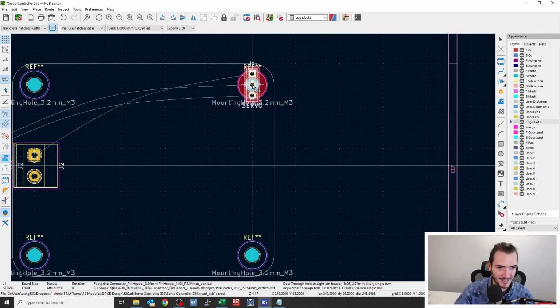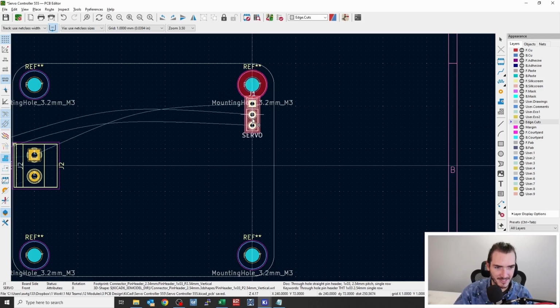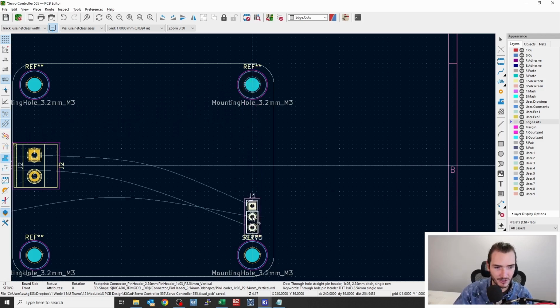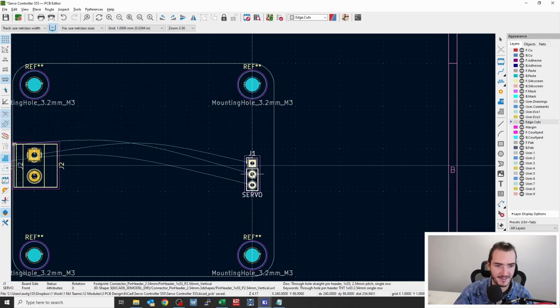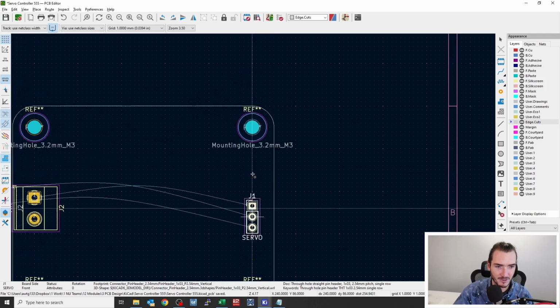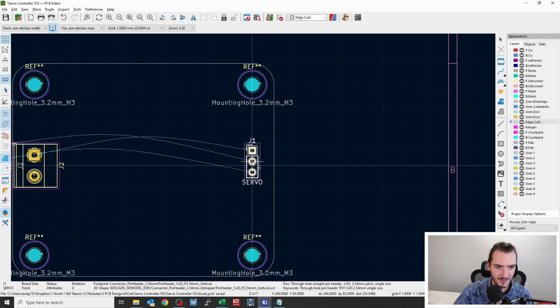If I wanted to go down, I could drag with the mouse, or I could just use the down arrow key, hold down Control to go in jumps of 10. And Shift will move the screen with the arrows. So you can use those in combination to get very exact movements.